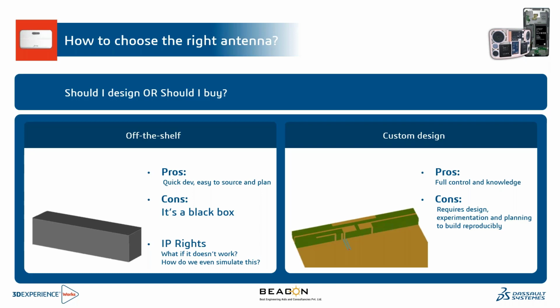Whereas custom design is better because, with the help of Antenna Magus, we can come up with a few designs which are suitable for placing the antenna in the respective position for the given gap, and we can redesign or retune it to get the performance that is required. So rather than spending on an off-the-shelf antenna, we can custom design with the necessary libraries which are available within Antenna Magus.